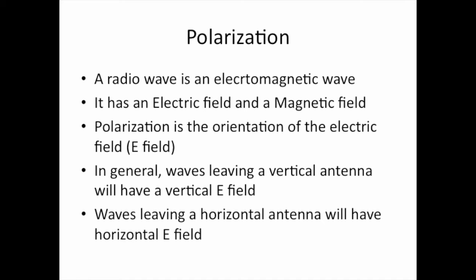Circular polarization implies a uniformly rotating electric field. Things are not really uniform in nature. That's why, with a horizontal antenna, you can receive signals quite well that have been radiated from a vertical antenna, once they have traveled to the ionosphere and been refracted.